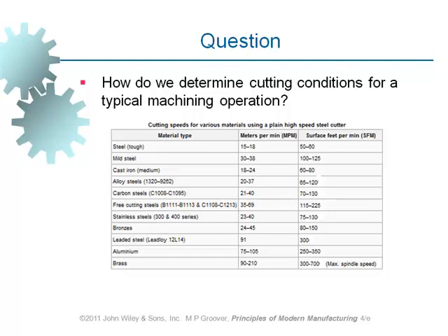As you can see, for example, if we are making use of high-speed steels, depending on the type of the material being cut, we've got to make use of the right cutting speed. And the range of the cutting speed is given here. For example, we are cutting alloy steels, and we are making use of high-speed steels. For alloy steels, the range of the cutting speed is between 20 to 37 meters per minute. Now the question that I asked before is again, what is the right value of cutting speed within this range? How do we decide that?